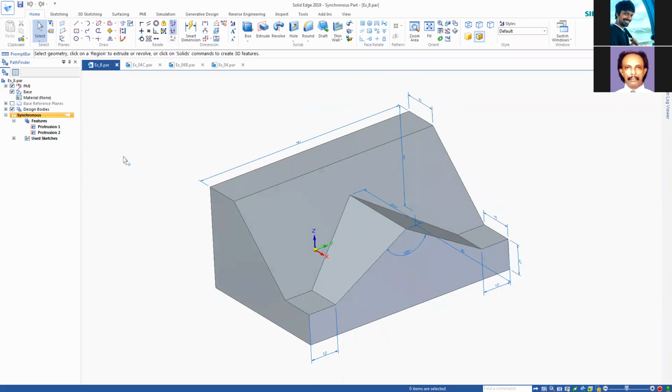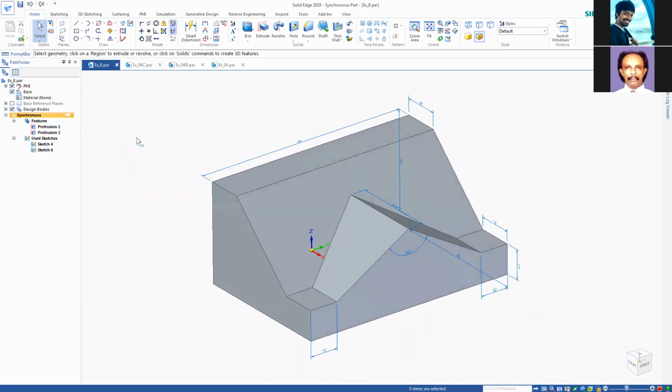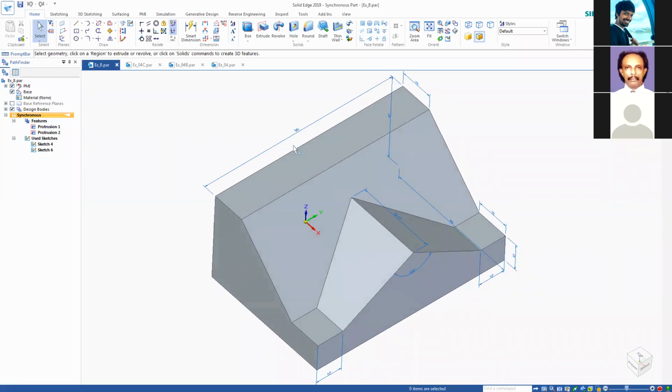Right. And if you see this, the Pathfinder, there is something called the used sketches. You don't find that one in ordered modeling because sketches are associated with the features. You cannot get rid of the sketches because they are linked already. And also the history, parent-child relationships, and everything is there in the ordered modeling. And this PMI is product manufacturing information. So straight away you can see the dimensions are there. I can straight away change these dimensions.